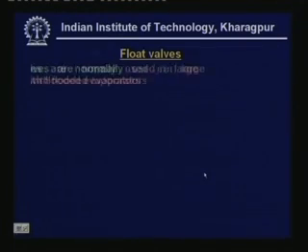Of course, one possible solution is to have a perfect counterflow type of evaporator, okay, where you can have close approach, yet you can use the thermostatic expansion valve. Okay. Now let me quickly explain the float valve.